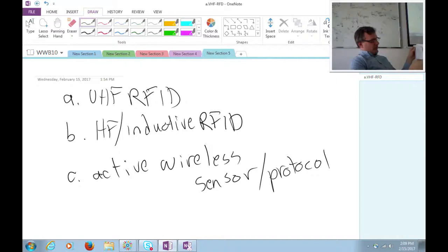An engineering design firm proposes a small, low-cost, no-maintenance device to put in a vehicle windshield so that residential cars may automatically open and enter a gated area. Yeah, I would say A. That's essentially an AVI system, automatic vehicle identification. It's got to be no maintenance, no battery. That means passive. And generally, if you put it on the windshield, you need far field interrogation to get that to work.